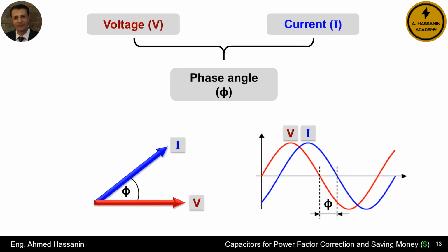But when it comes to the form of the current, we must understand that the presence of voltage and current at the load creates a phase angle between them. As I mentioned earlier, the basic elements of any electrical load are resistance, R, inductive reactance, XL, and capacitive reactance, XC. These elements are responsible for shaping the form of the current.